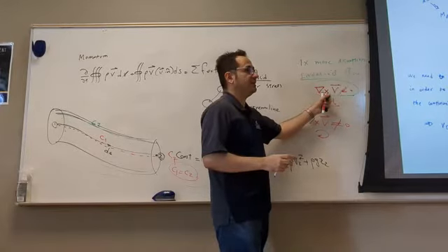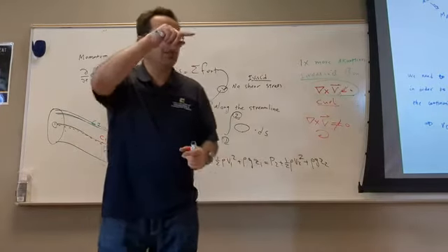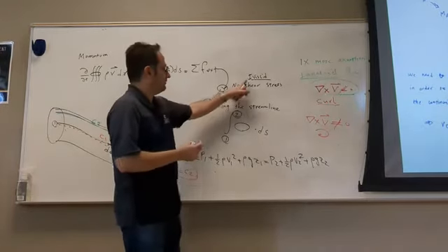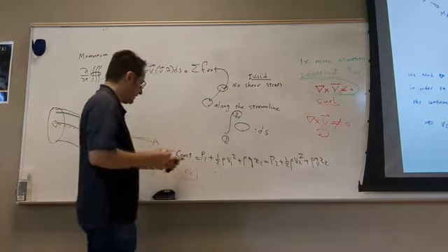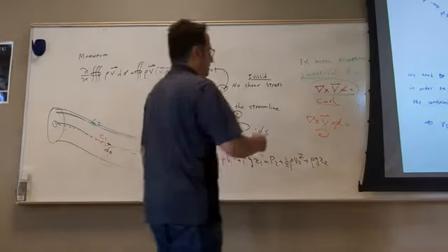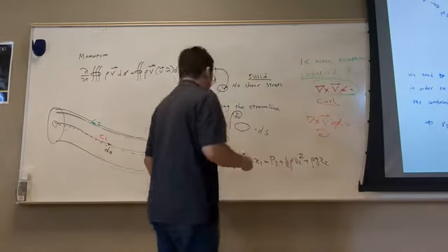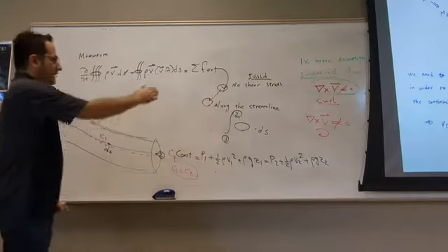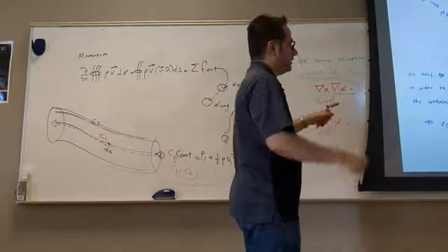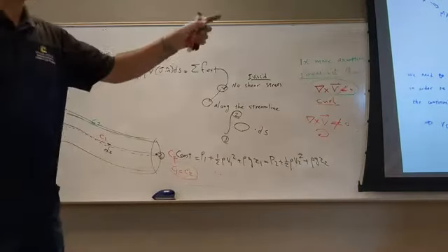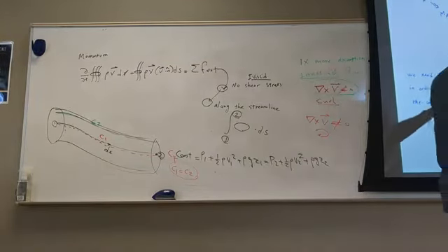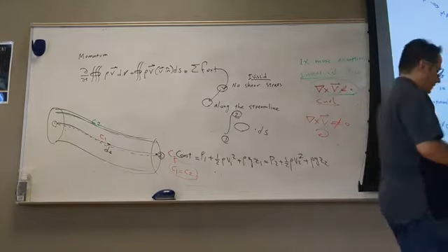Why? Because in real life, when you have viscosity near the wall, you have rotation near the wall, right? And also, when you have viscosity near the wall, it's not inviscid. So basically, you can't write the Bernoulli equation near the wall or in the viscous region. So we make two assumptions: irrotational and also inviscid. Now we apply this in this equation, and I'll show you why we make this assumption in order to make it closure. But you didn't have to do that in the midterm. In the midterm, you just make it very basic. You write this equation, which I saw a lot of people do, and you just solve it. So let's go ahead and finish that.